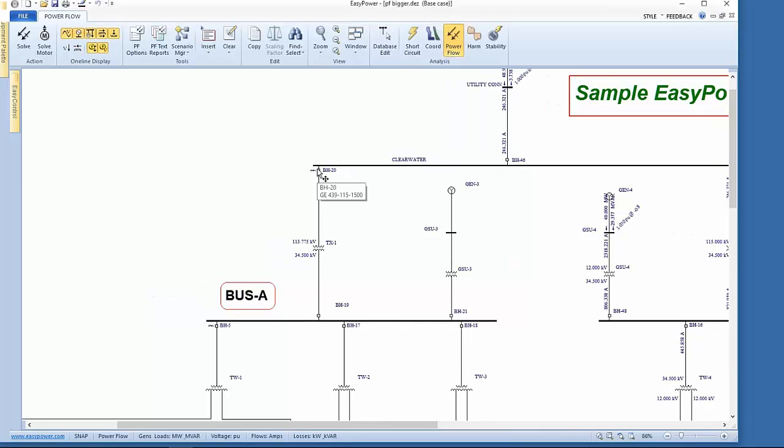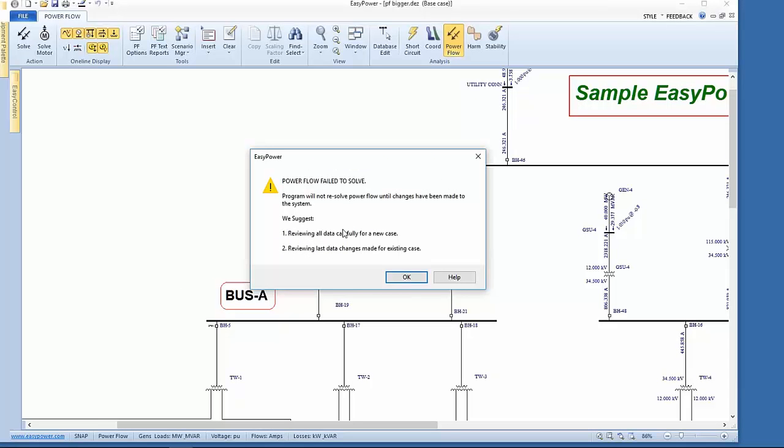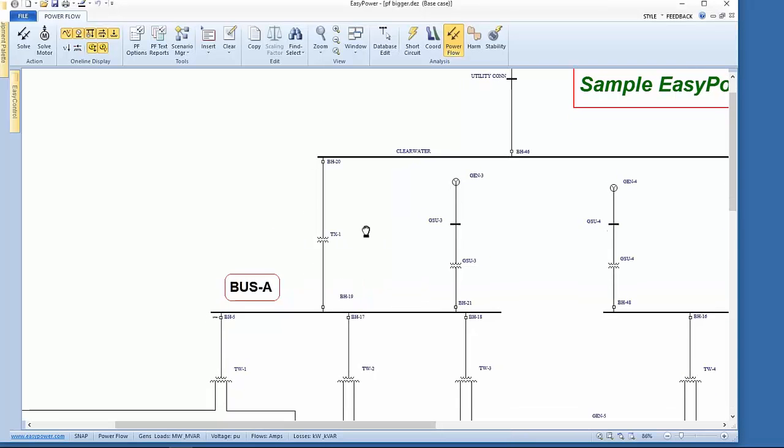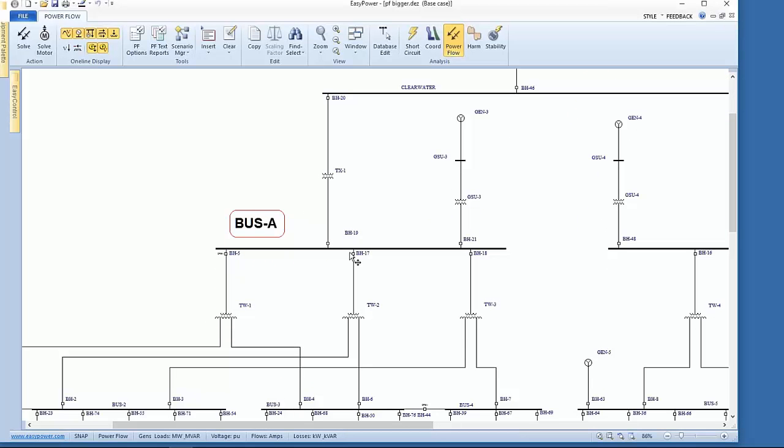So as I close this particular breaker, sure enough, I get the indication that I have a problem. And personally, I like to follow the same kind of progression, and that is, okay, if I follow this load downstream, I'm going to go ahead and open these 3 breakers.